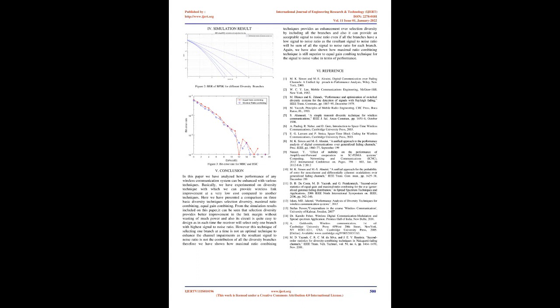Maximal ratio combining may be used in nearly every diversity application, but at a significantly higher cost and complexity than other diversity strategies. Figure 2, Maximal Ratio Combiner. MRC is the popular term for this, and usually, in the diagram, X is sent through a channel with a coefficient of H, and received through one antenna with a particular weight factor.